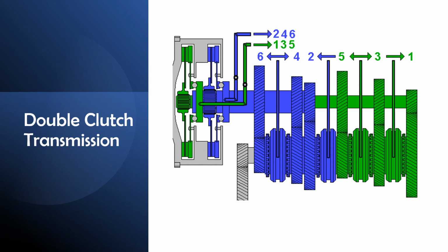The secret of a double clutch transmission is that the gears are selected at the same time, while one clutch is closed and the other is not. This makes it possible to shift incredibly fast. For example, gear 1 is selected, then gear 2 on the other shaft is already selected, but with the clutch open. When there's a gear change, clutch 2 closes, and if you accelerate more, clutch 1 opens and gear 3 will be selected, and so on. So you have, in every case, the next gear you want selected. This is controlled by a mechatronic.